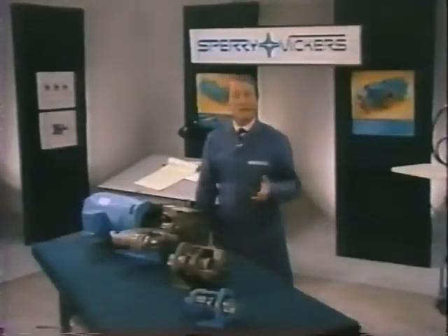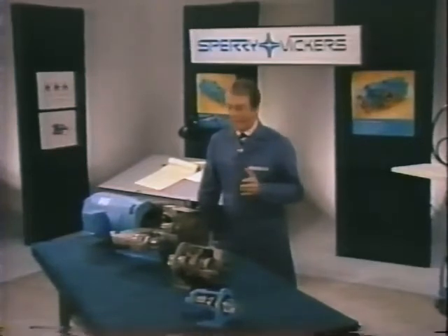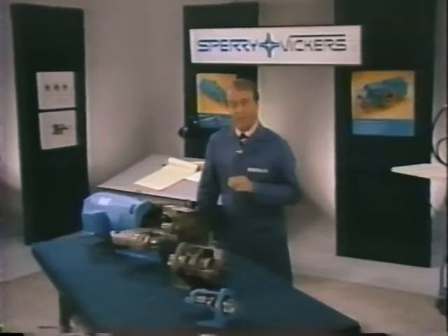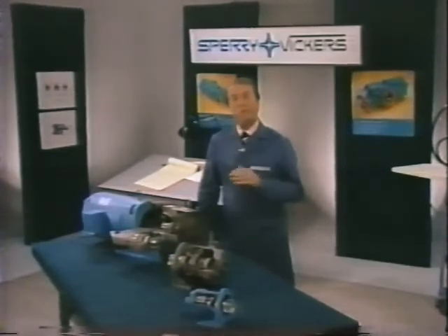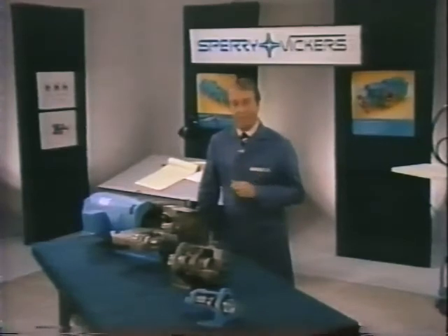If we were to install a larger hydraulic motor, it would develop more torque, but since it would require more fluid per revolution, its top speed would be slower. A smaller motor would, of course, turn faster, but develop less torque. In each case, however, the torque would be independent of speed.